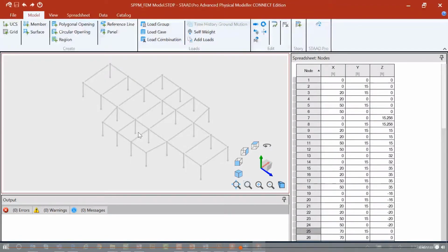The physical modeling workflow is used to model your structure in the STAAD.Pro physical modeler using physical members. The physical model is used to draw structural elements as they are physically constructed. So let's visualize, say, a beam to girder scenario. Typically in the STAAD.Pro analytical modeler, if you have a girder that's supporting some infill beams, you would segment that girder member so that it shares common nodes with those beam members. That ensures proper force transfer through the analysis process.